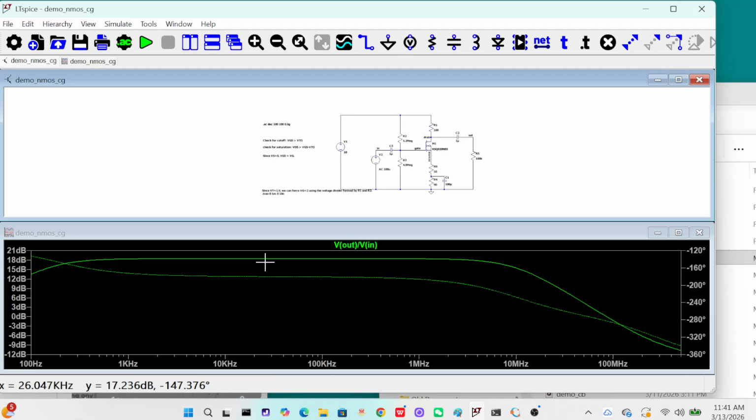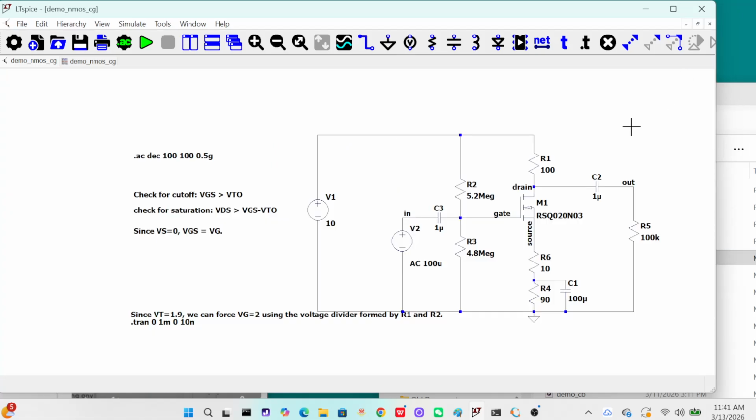So it's now 18 dB. Or equally, you can use a variable resistor here and just use the potentiometer, and then you just vary the resistance. The core resistance will remain the same, but by doing this, you will change the gain without changing the bandwidth.